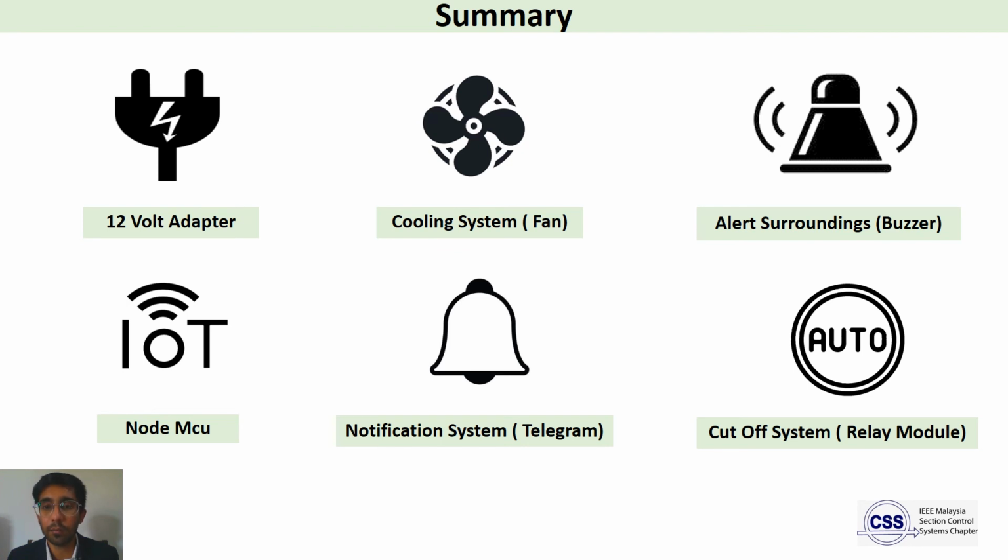In this system, the user is able to set the desired temperature for the system to monitor based on the local requirement. The humidity and temperature sensor, which is the DHT11, functions to monitor and detect the value of temperature and humidity, which is then displayed on the LCD screen. To illustrate, if suddenly the temperature of the machine is at the maximum level, which is 43 Celsius, the relay will automatically cut off the machine power supply, which means that the machine cannot operate or function.